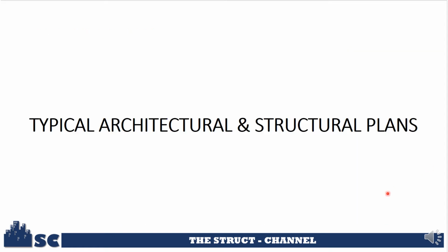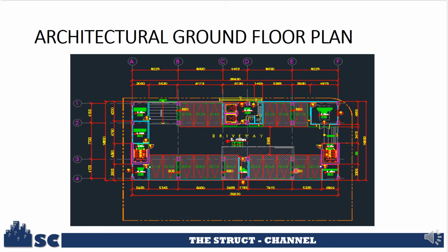Now, for the typical architectural and structural plans, the ground floor of the building is an open parking. Therefore, columns must be minimal and wide openings should be provided on the entrance and exits of the ground floor for the cars.